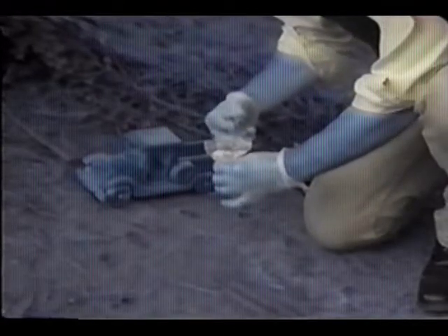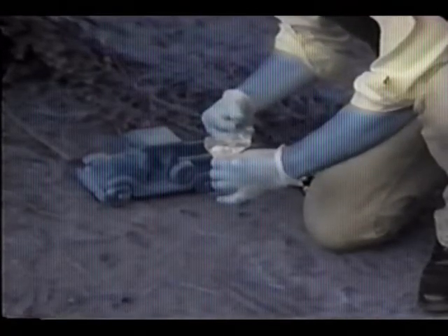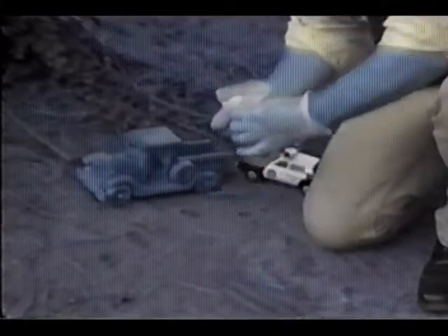Take core samples from the top 1/2 inch at each location that you've selected and place it in a Ziploc bag. Use a separate bag for each composite sample, but not for each sub-sample. If you see paint chips in the sample, do not attempt to remove them. Try not to include twigs, stones, grass, and other debris. Remember to double bag unless you're using a 4 mil thick bag.